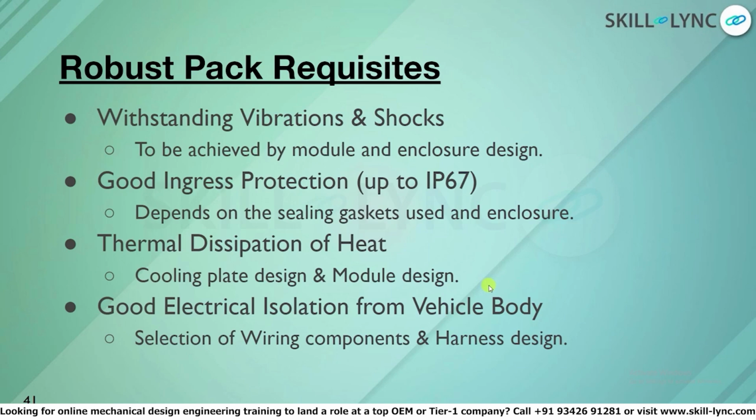from the cells. And then you need to have a very good electrical isolation for the vehicle body. So there has to be no live current coming from the electrical parts, especially the battery pack. So you need to select the right wiring, and you need to see that all the current carrying wires are shielded as much as possible.